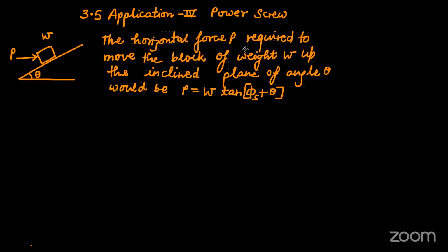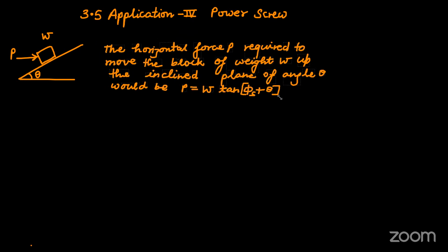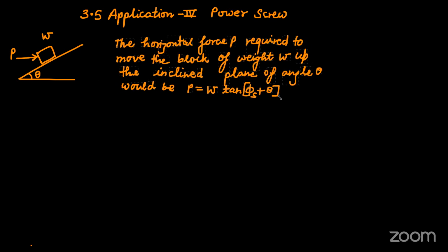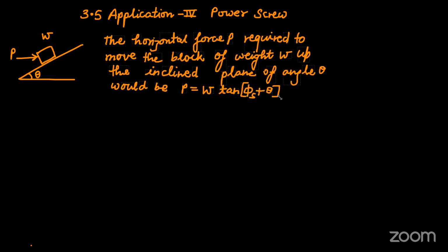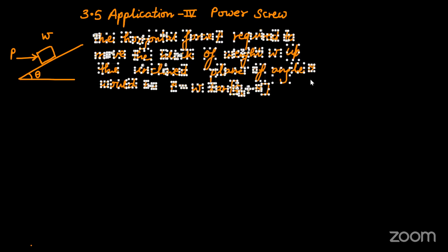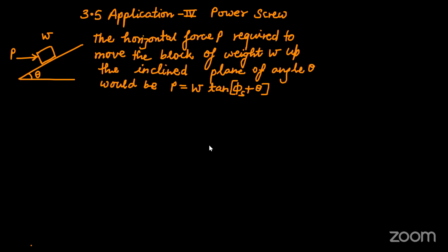Sure, angle of friction, sir. Angle of friction? Angle of repose, sir. Sorry, sir, angle of friction. It is the resultant reaction angle from the normal reaction, sir. No, it's the limiting value of that angle, isn't it? When you apply a force, friction is going to act, and normal reaction is going to act.